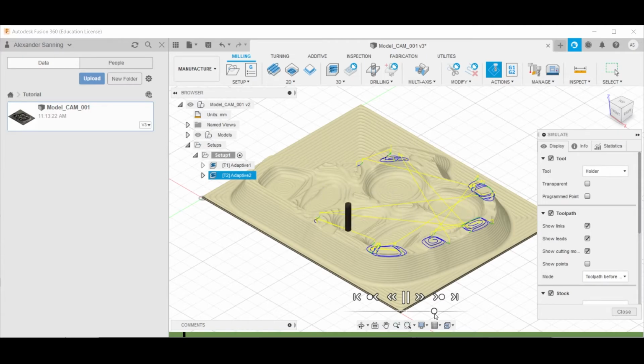And like you see, there are a lot of travels. And while travel time is not lost time, travel time is not active milling time, so one might feel that it's a very ineffective way to mill. But it is still more effective than to try to use a smaller diameter mill to clear all the material in one go. But this is also something that you can experiment with.